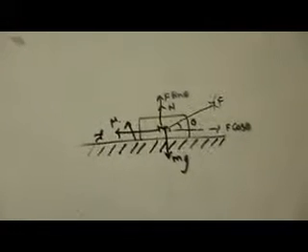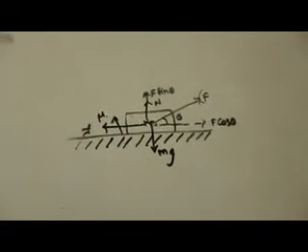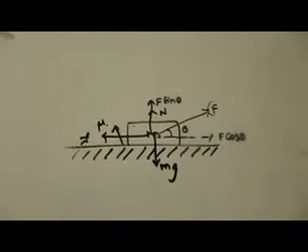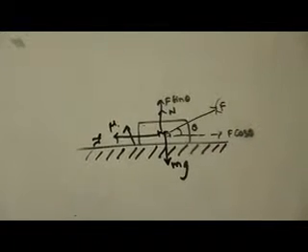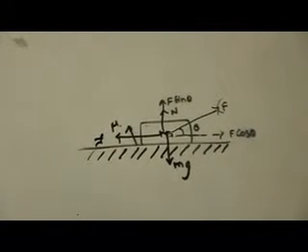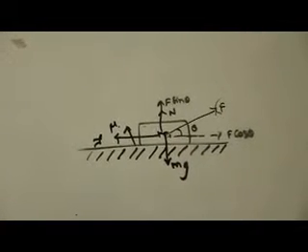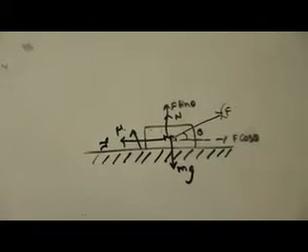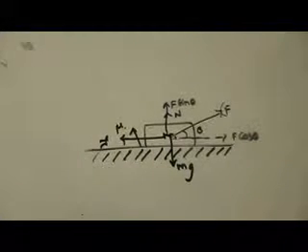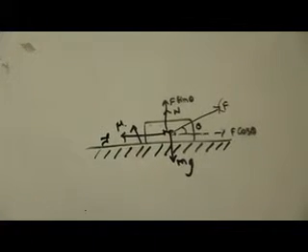What do we mean by the minimum force required to move? The minimum force required to move is the force required to move the body with uniform velocity or just about to move. There is no necessity for the body to accelerate. Therefore, finally what I can say is, whatever the maximum limiting frictional force that is created, if the same amount of external force is applied, then it is enough to move the block. That is the minimum force, and if you apply more force than this, the block just accelerates. And you are being asked for the minimum external force required to start the block to move, right? Therefore it will be just equal to the limiting frictional force.